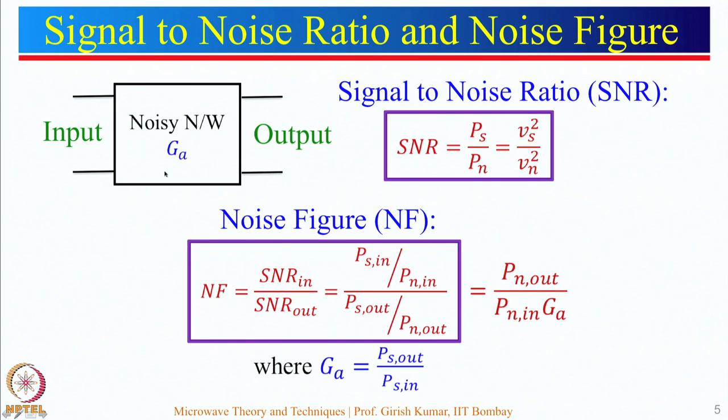Let us start with the transistor. A transistor amplifier would have several resistors. It will have a few PN junctions. So those PN junctions can be then represented by noise current. So the entire amplifier circuit can be represented in terms of its Thevenin equivalent or Norton equivalent. So what is a Norton equivalent? That will be a current in parallel with resistor. So we can say that any amplifier can be ultimately simplified to a noise current and a resistor. So we have already seen what are the noise current and resistor.